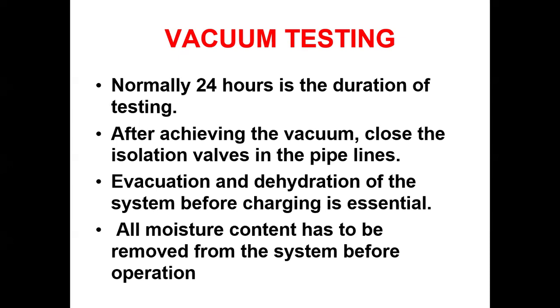Otherwise, in some other scenarios, the values are mentioned in microns. For example, at my site, we started at 8 p.m. for only 12 HP, but it's on the 11th floor and the terrace is on the 12th floor itself. So we have a large distance of copper piping. We waited for about 24 hours, and the reading should be maintained at 500 microns, but it started at 300 microns. So we need to wait more time until it reaches 500 microns.